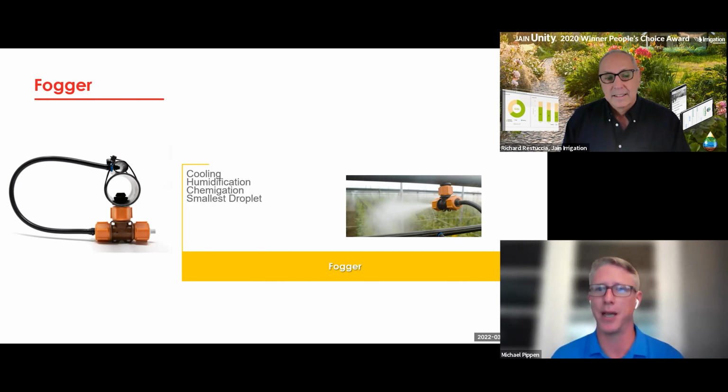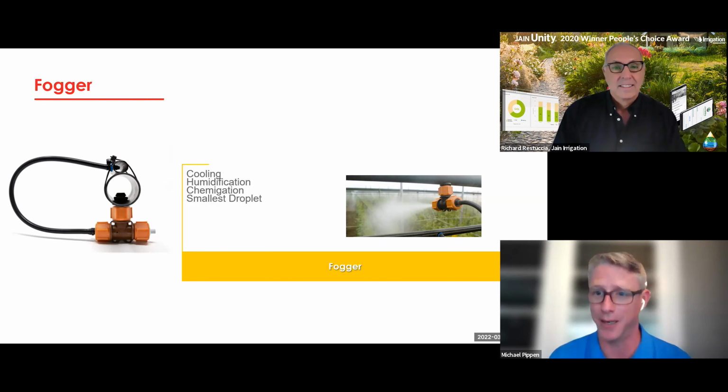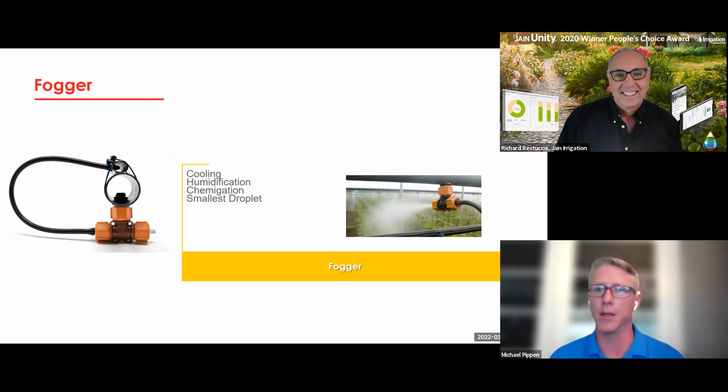A pound or two of pressure change in an irrigation system on the water side is really not going to change our output very much. It's really going to have very little effect on our uniformity in most cases. But let's say a 5 PSI difference in air can be quite significant. Think about your car having 30 pounds versus 35 pounds. At 35 pounds, your light doesn't go off, but at 32, it does, right? And so the air pressure is a tighter range that you have to operate in.